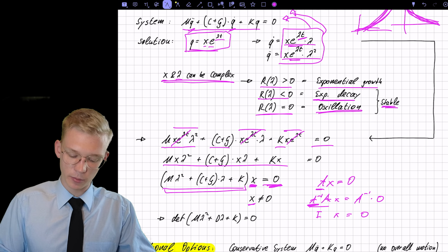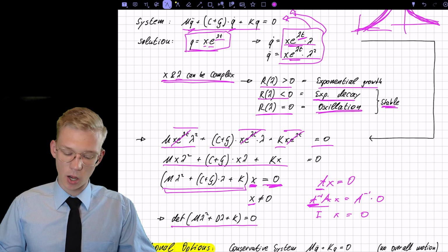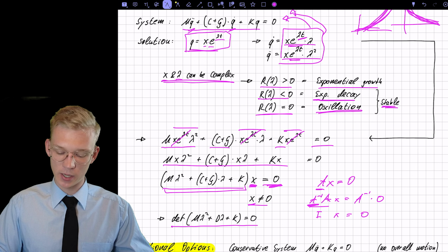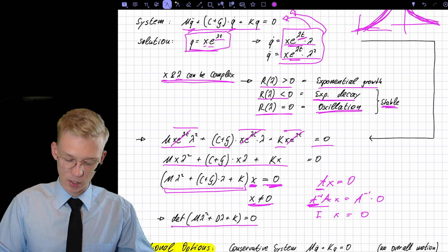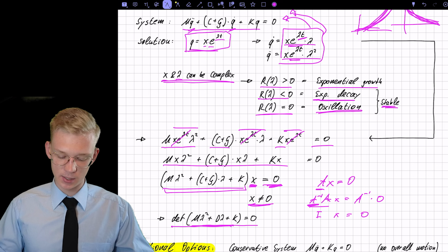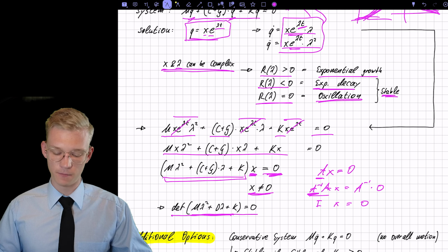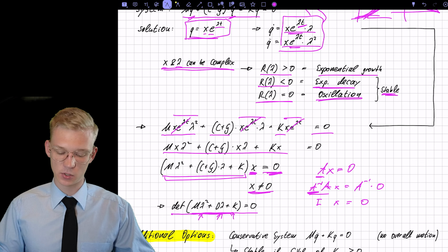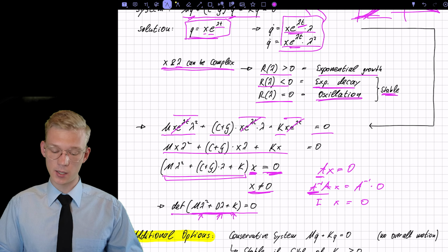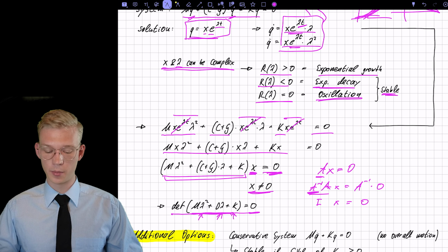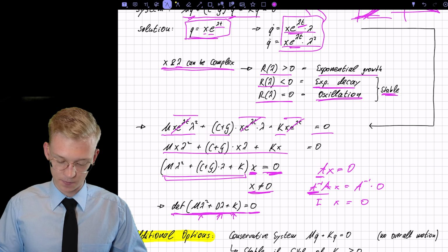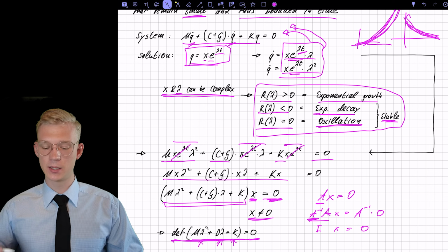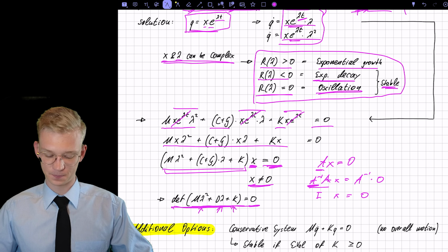And a matrix is invertible when the determinant is non-zero. But if the determinant is 0, you can't invert it. And this is how we get rid of our trivial solution x. So we take the determinant of this matrix and then have to basically just look at our lambdas. How do we need to set the lambdas so that the result of this equation is 0? And depending on those lambdas, we can then decide if a system is stable or unstable.